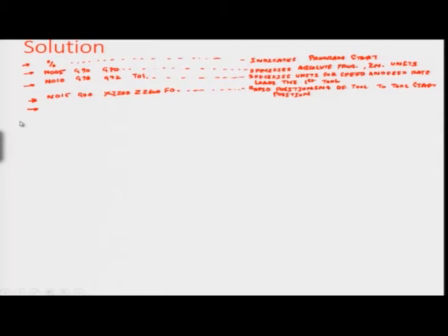In the next line, we would like to put another command, N020. In the first instance we would like to shave off 0.1 inches, so what is going to be the basic extent up to which the tool needs to go? If it is 0.1 inches on a 2 inch diameter, it means that radially 0.1 inch corresponds to the final diameter being 1.8 inches.